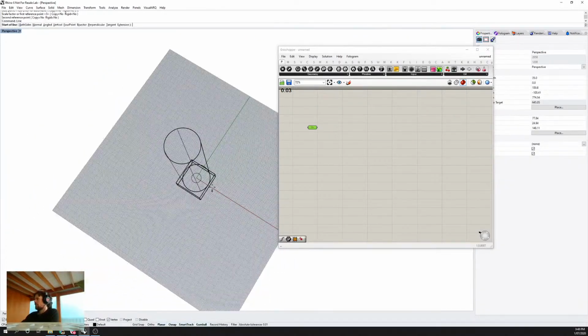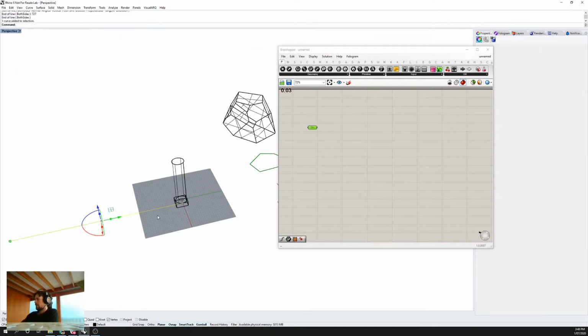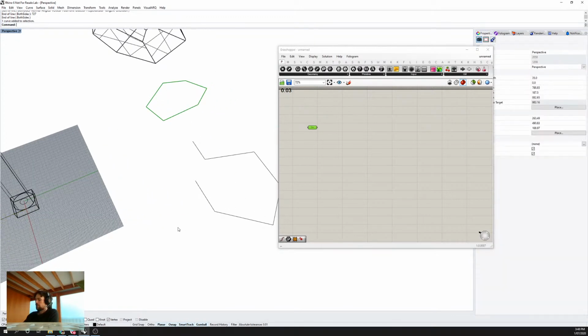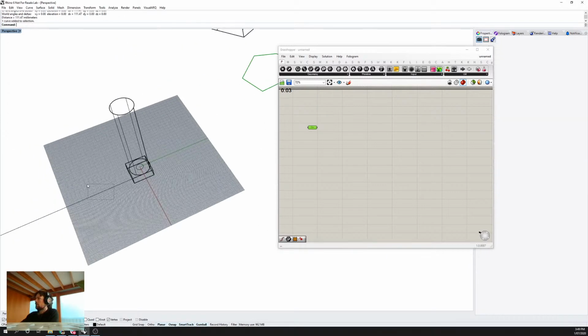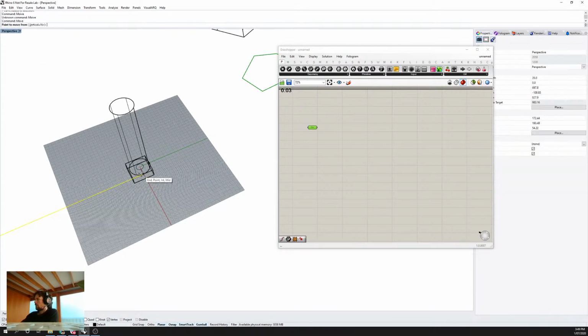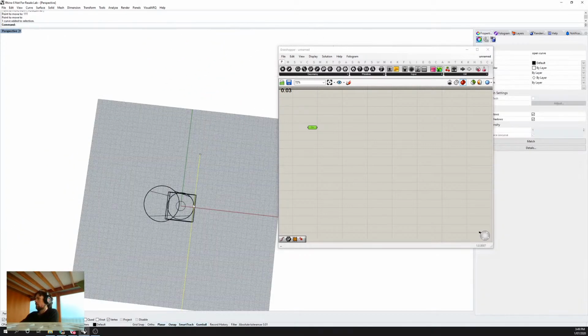Right, so again, just to explain the logic. So I've got a 727 mil long part. There it is there. And then let's say the first bend I'm going to do is this bend here. So I might check, okay, well, how long is that bend? From there to there, it's 111 millimeters. So I might move this 111 millimeters that way. So now I know, okay, I've got my length right.